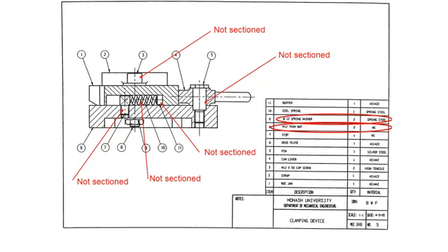On here, it's also good to note we have also included the scale. You might have noticed we haven't included a projection system, and that's because we've only got a single view and it's not needed. You can't tell whether it is a first or third angle projection, so we don't need that. So that finishes up everything we need to discuss with assembly drawings.